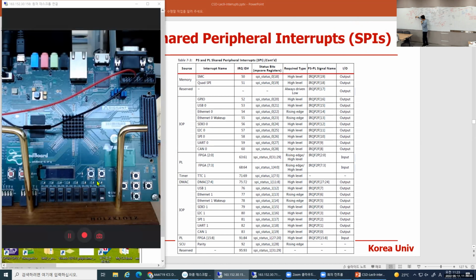Here we have a GPIO that is connected to that switch. That switch we can push up and down. So 8 switches, GPIO, your custom logic. If you push up or down, then an interrupt will be generated that will be delivered through the distributor, the CPU interface, and finally the CPU. Let's do that. Let me show you a demo. For that, you need to instantiate a GPIO and then open up that interrupt connection. Let me do that for you.